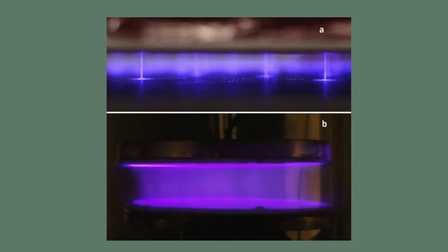This self-quenching property is the key innovation of the DBD. It prevents the transition from a non-thermal, filamentary discharge to a thermal, high-current arc, which would occur inevitably at atmospheric pressure in an electrode system of two metal electrodes without a barrier. The dielectric barrier acts as a distributed, current-limiting capacitor.